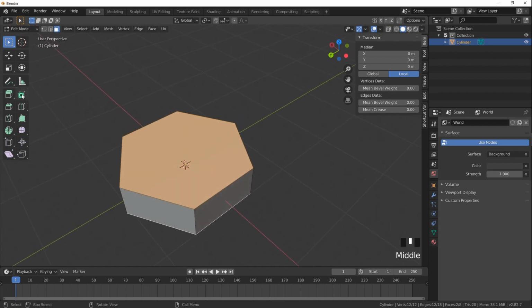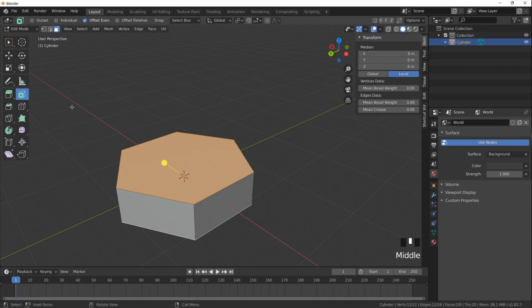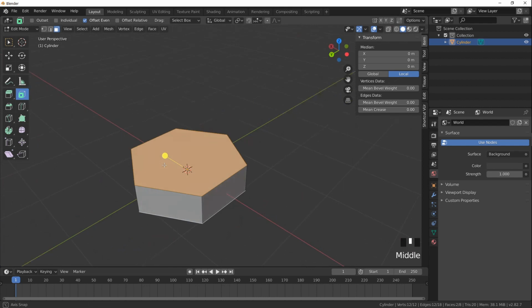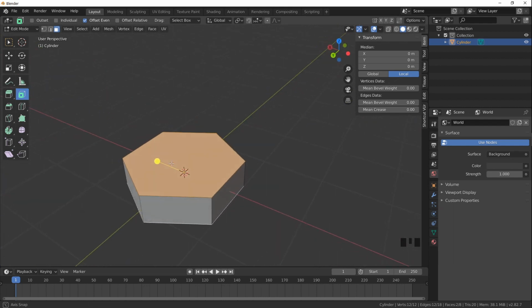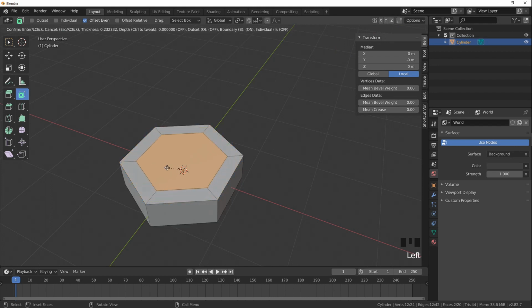The Inset Faces is this tool that we have here. In Blender, those tools work as active tools, so it means that if I'm using the Inset Faces tool, I'm able to do the same operation several times. Now I already selected 2 faces in the meantime, and if I use this widget here, I can make this inset inside the faces.